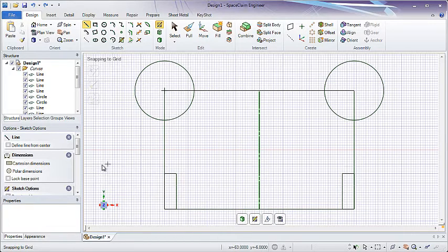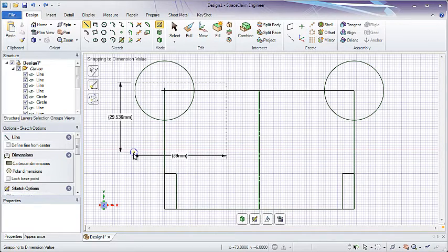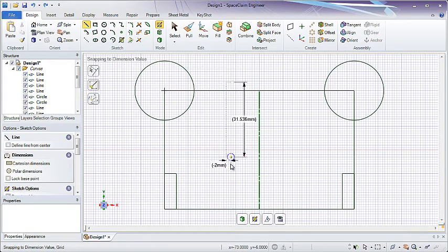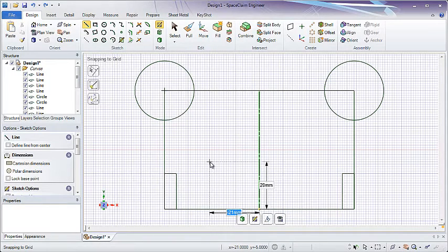should be. In the Options panel, if you click Cartesian dimension, you can set where you're defining the sketch to start from. Notice the base point I'm moving around with my cursor, and I'll click on the corner here of the mirror line and the bottom line that's there. You'll notice the line that I'm going to start to draw is going to be a certain distance from that corner. And you'll also notice near my cursor there's dimensions that are positive.